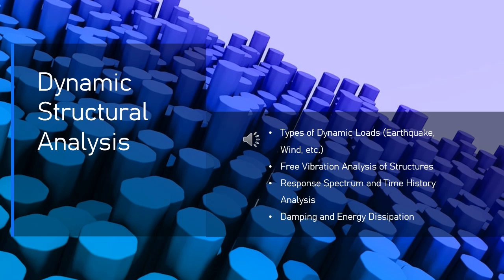9.5. Importance of free vibration analysis in structural design. Free vibration analysis is important in structural design for the following reasons. 1. Resonance prevention. Resonance occurs when the natural frequency of a structure coincides with the frequency of an applied load. This can lead to excessive vibrations and structural failure. By identifying natural frequencies, engineers can design structures to avoid resonance with common dynamic forces, e.g., wind, traffic, machinery.